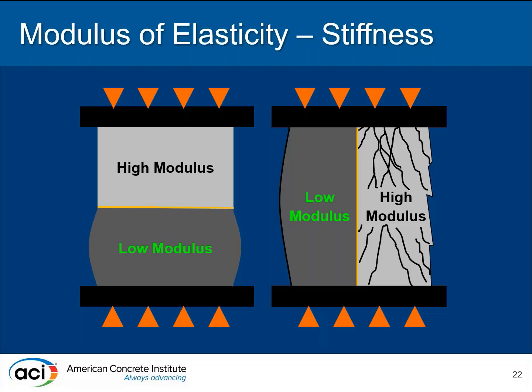The higher strength concrete is stiffer, so it attracts more load, and it participates more in the load sharing than the increase in strength. So you can get in the right situation, or probably really the wrong situation, where you end up with premature failure of your beautiful, high strength, really important and well made repair material.